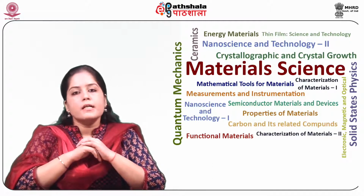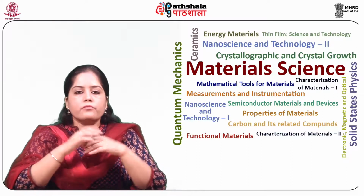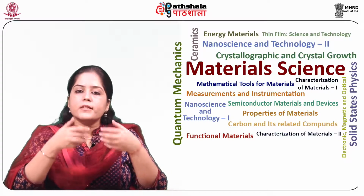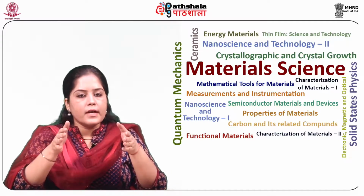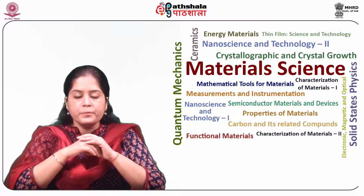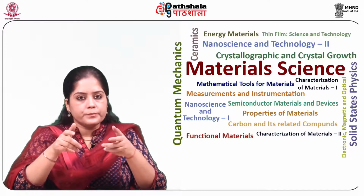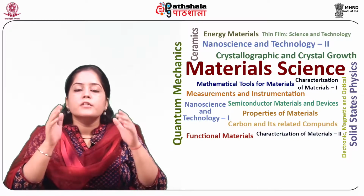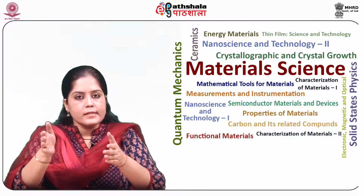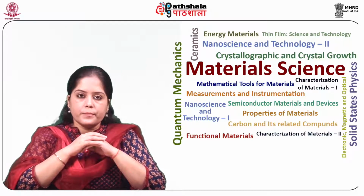So students, let us now discuss the historical background of the Gunn devices. The reason for the alternative name, transferred electron devices, is that their operation depends on the transfer of electrons between two different valleys in the conduction band of the semiconductor.